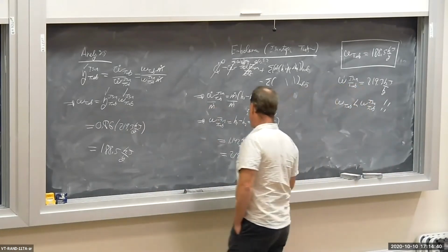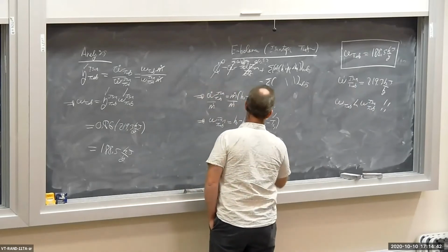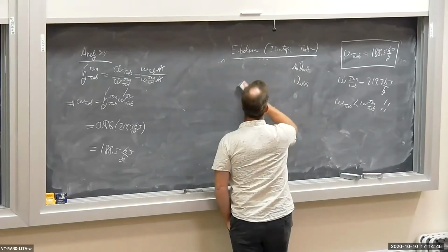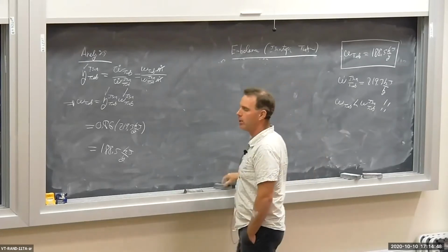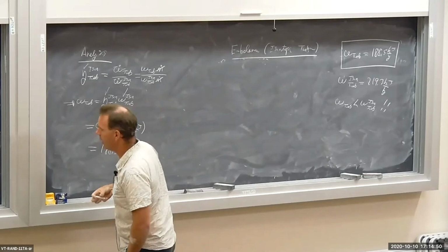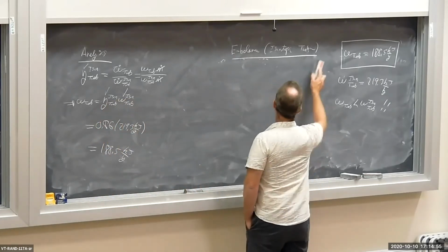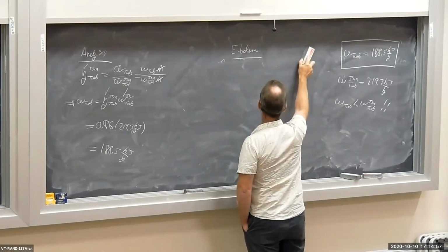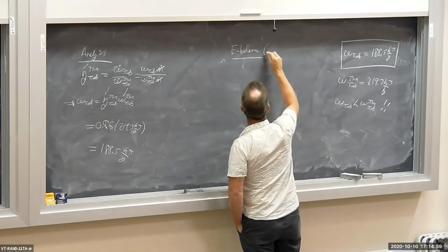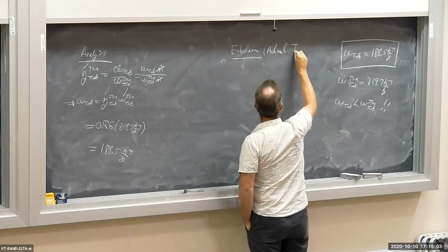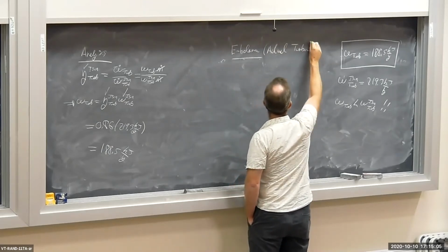Let's calculate the actual outlet temperature, T2, for the real turbine. We've already calculated T2 sub S. What was that? 1008 degrees. Let's calculate T2. Let's apply the energy balance to the actual turbine.